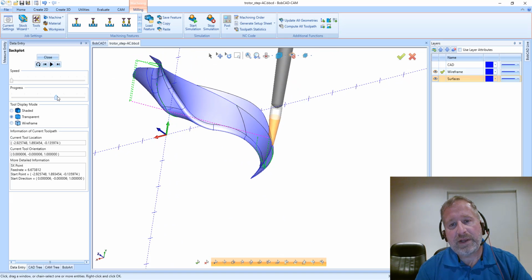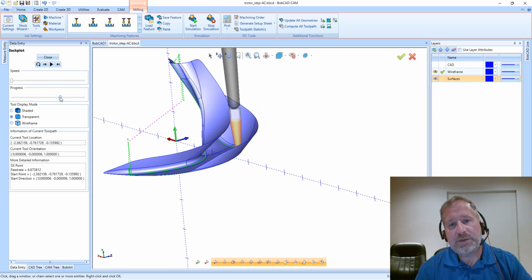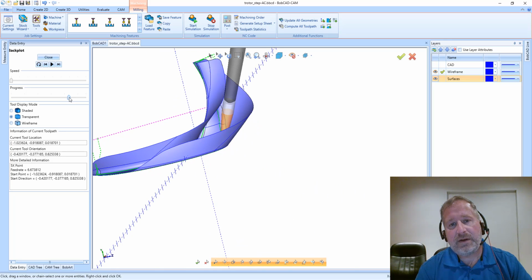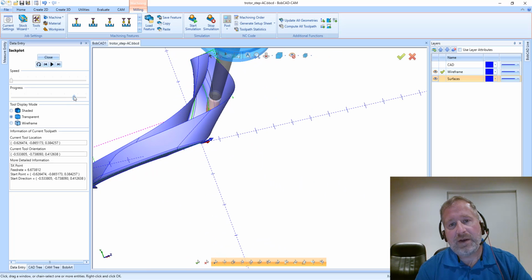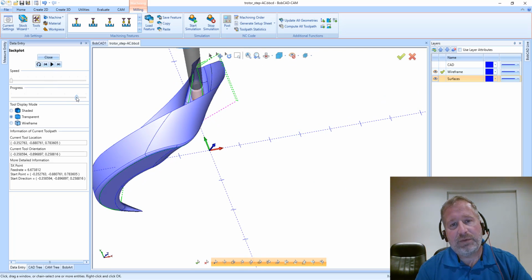So that's starting with a gouge. We can see that we have much more clearance angle here this time compared to the last. And as we get into this heavy transition, okay, so we're gouging some there. The tool's kicking around. We're actually only gouging just a little bit here now.